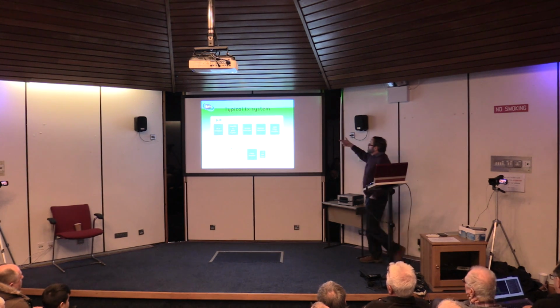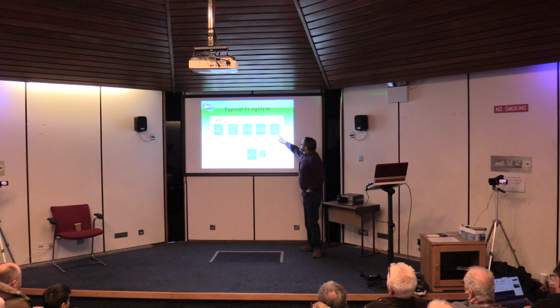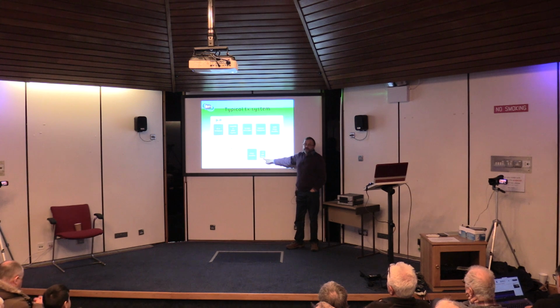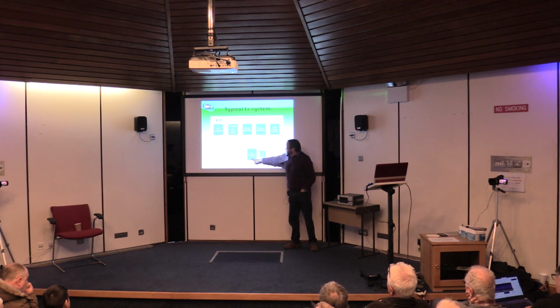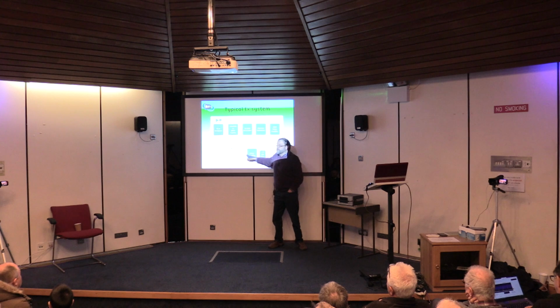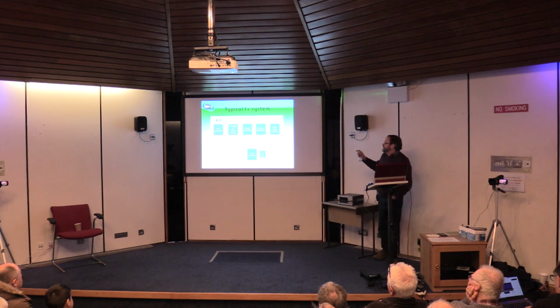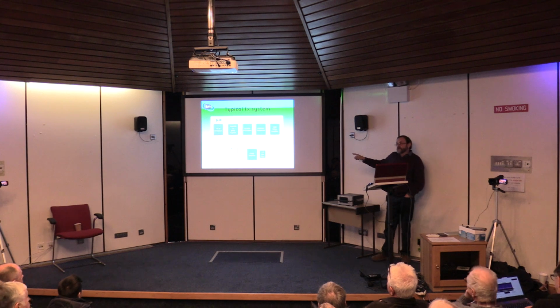And so most of us are now finding that we're having to use some form of driver amplifier at 2.4 gigs, and then, note the filter, and then the power amplifier with a very short lead to the dish. That's fairly typical of what people are doing.